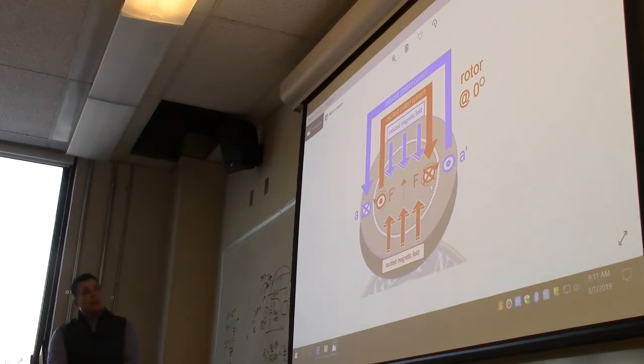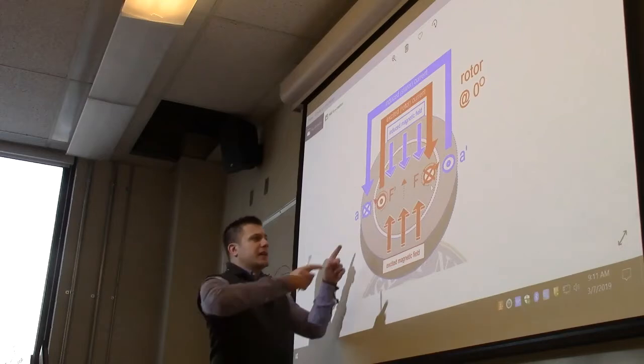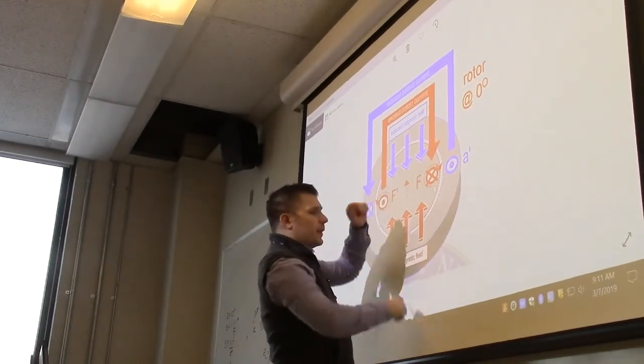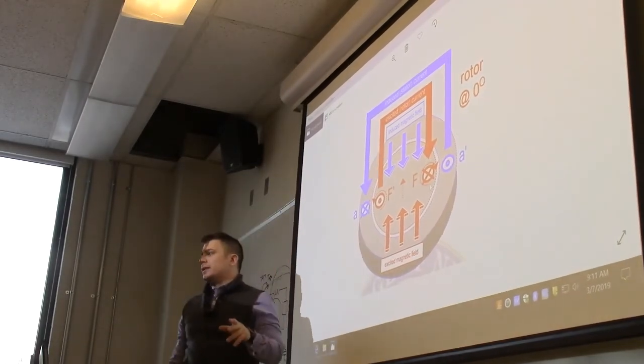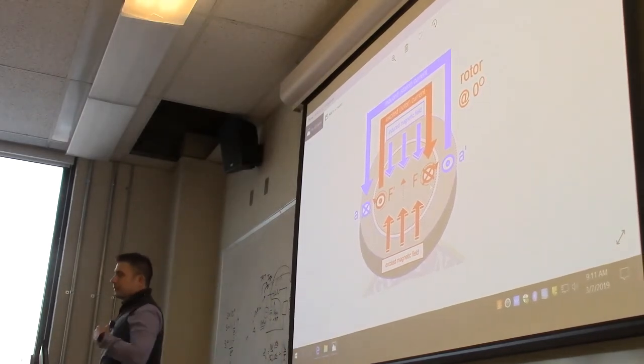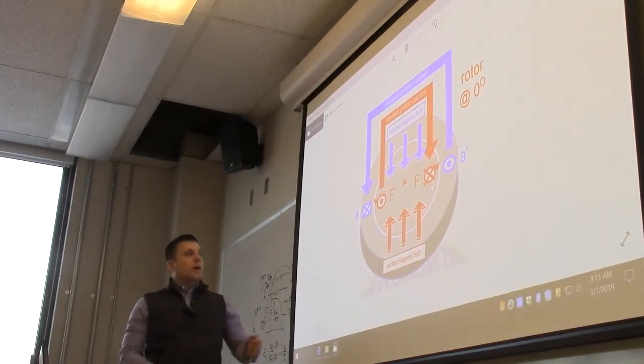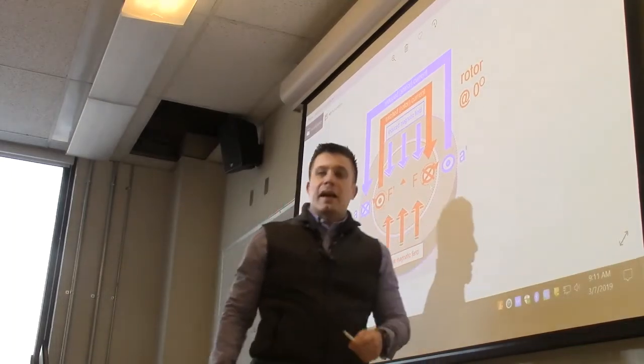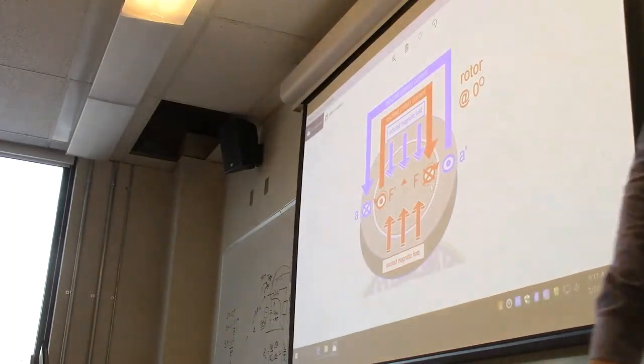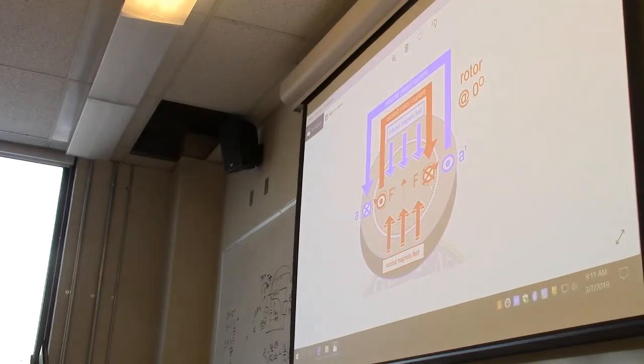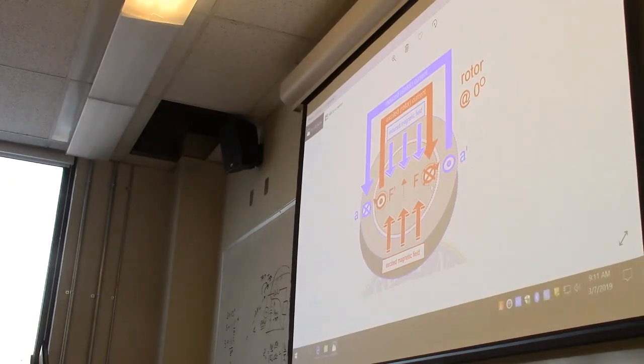So we have the rotor, which is in the middle. We have the stator, which is on the outside. We have stator windings, which you have one set here, here, and here. I think we looked at a diagram that was similar to this in that first lecture, the PowerPoint lecture that we did. And then we have the field winding, which usually there's only one set of. And this is where the number of poles comes into play. If you only have 2 poles or one set of poles, you only have one field winding. If you have multiple sets of poles, you would need multiple field windings.